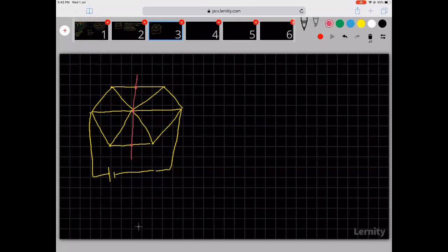Because left side and right side are the same, they'll all be at the same potential, exact midway. So if this is 10 volt, this will be 5 volt, this will be 5 volt, this will be 5 volt. I'm assuming 0 and 10. If it was minus 5 and 5, it will be 0, 0, 0. Whenever you have such points, you can connect wires between them. So that is what I'm going to do.